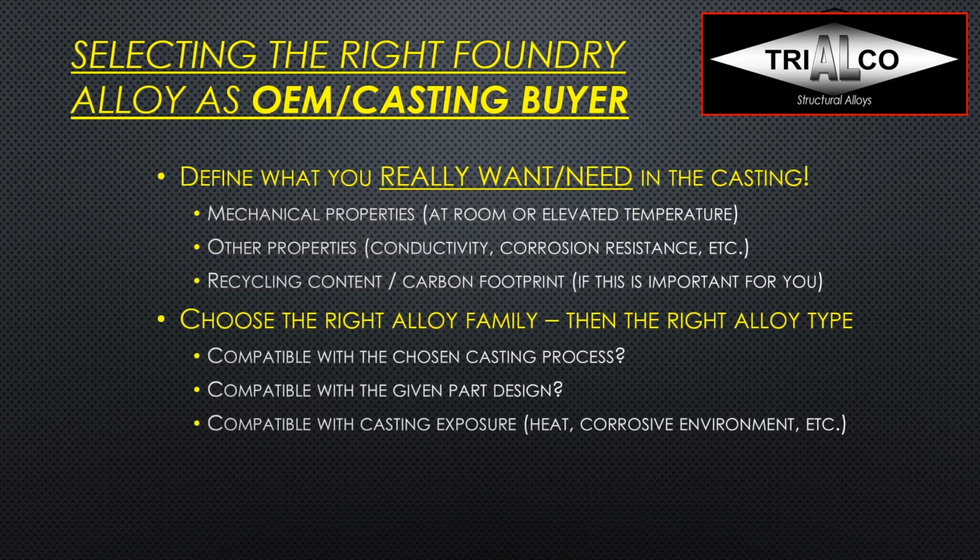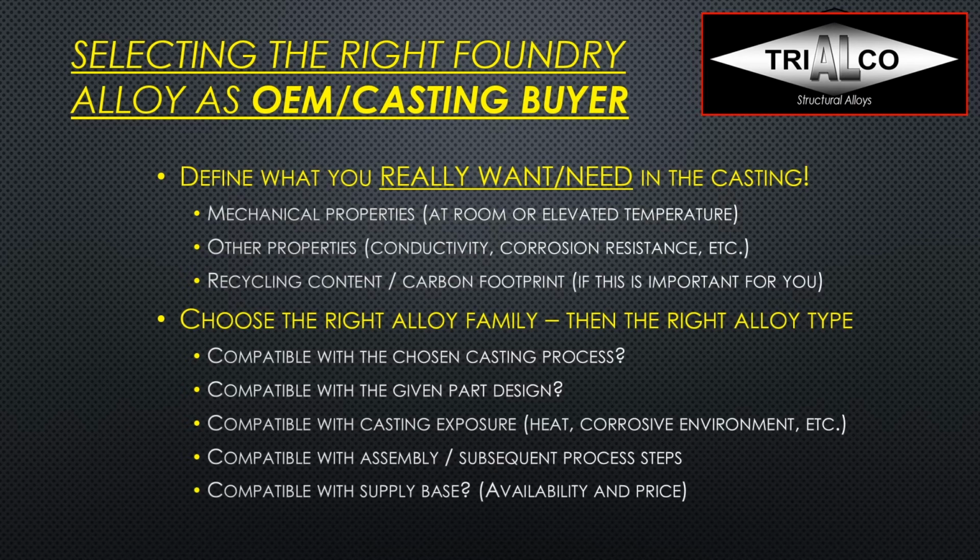And is it compatible with casting exposure, whether it's exposure to heat or a corrosive environment? For example, aluminum copper alloys typically are not as corrosion resistant as especially the aluminum magnesium alloys. And is it compatible with the assembly, all your subsequent process steps? Let's say you want to have it anodized afterwards. Well, that limits your alloy choices. Then you might have to go to a 500 or 700 series alloy. Finally, of course, is it compatible with your supply base? Because you might not want to end up with just one possible supplier in the world.